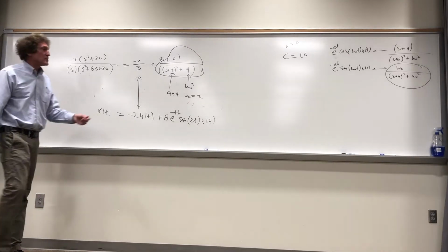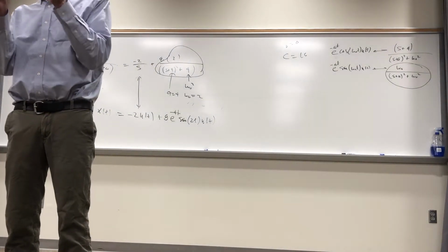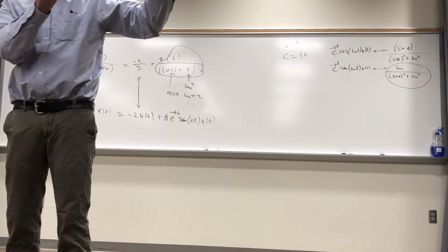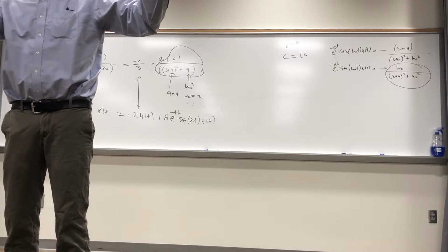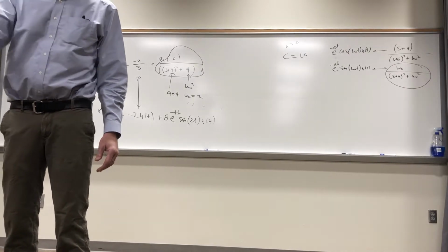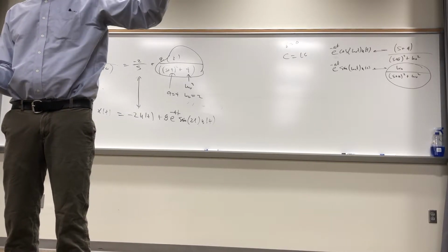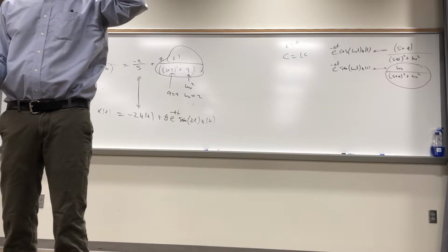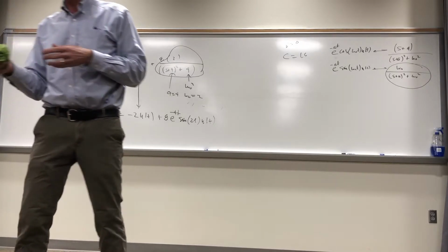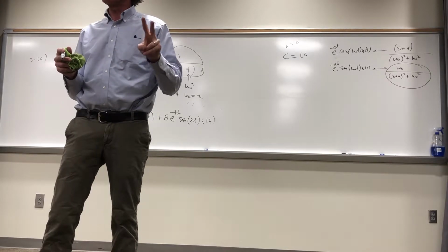If for whatever reason you solve for a b, you had bs plus c, then what you would have to carefully do is factor out the s plus a. You find a, you factor out s plus a times the coefficient, and plus another coefficient times your omega naught, because then you're going to have the omega naught over s plus a squared plus omega naught squared, and you'll get a cosine with an exponential e to the minus at and a sine times e to the minus at that are additive. And you won't have cosine of omega t plus 45 degrees or something like that. You'll never get that, but you will get a cosine and a sine together. Are we clear on that, class?